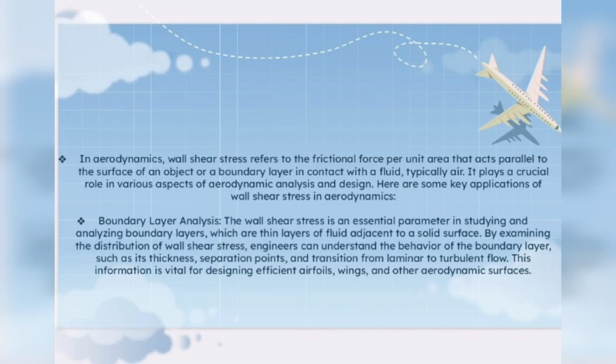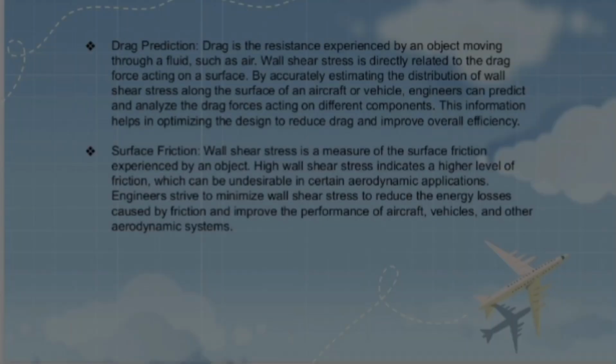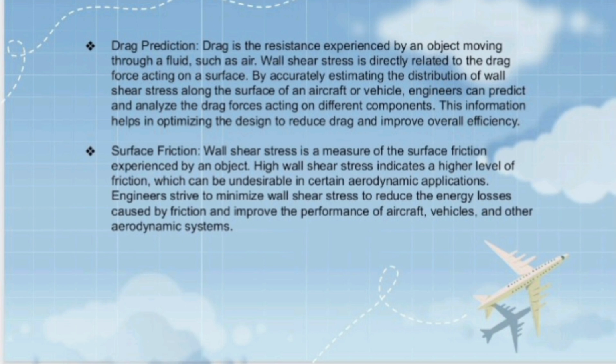By examining the distribution of wall shear stress, engineers can understand the behavior of the boundary layers, such as its thickness, separation points, and transitions from laminar to turbulent flow. This information is vital for designing efficient aerofoils, wings, and other aerodynamic surfaces.